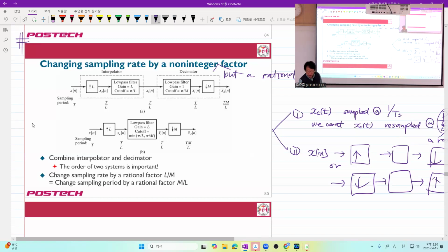And as you learned in the signals and systems review of this course, you can simply replace these two by the two impulse responses convolved as a single one. So you need to change the DTFT figure by compressing and expanding in the frequency domain and aligning.